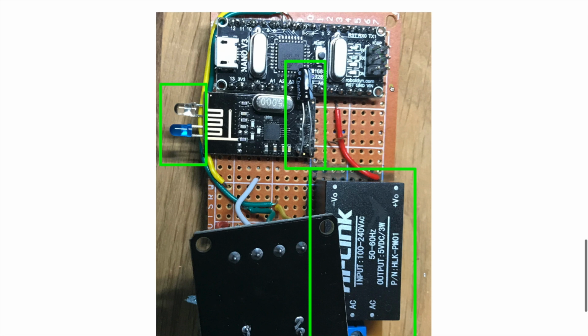By the way, to burn the bootloader, which I'm going to show you, you're going to need to use these pins with an AVR ISP, Tiny ISP, USB from the computer to these pins to burn the bootloader, and you can use it also to burn sketches instead of the USB.